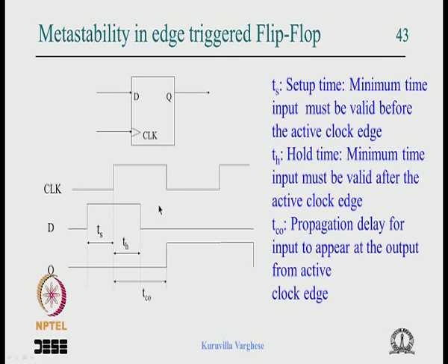Now this is the essential behavior of the flip flop. The data should arrive setup time before the active clock edge, and should remain for hold time after the active clock edge, and if so, from the active clock edge with some delay this output appears.